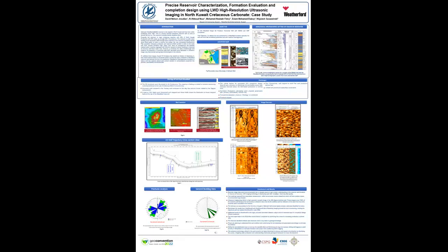To mitigate some of these issues, and also to have a better geological understanding, enhance oil production and minimize water cut, we are utilizing some of the latest technologies. One of the technologies is the ultrasonic imaging tool from Weatherford, and for the first time it has been used for this well, which proved to be very beneficial and in fact improved oil production for these wells.